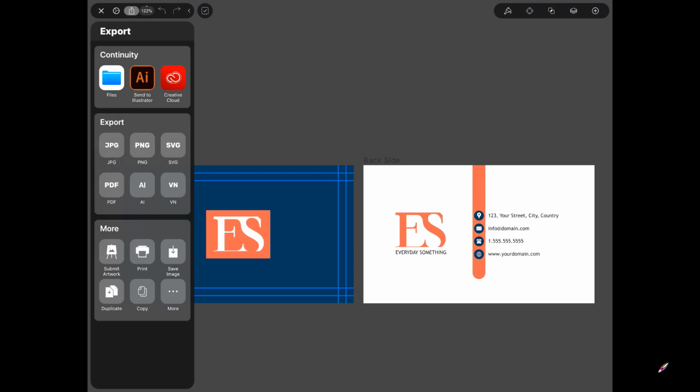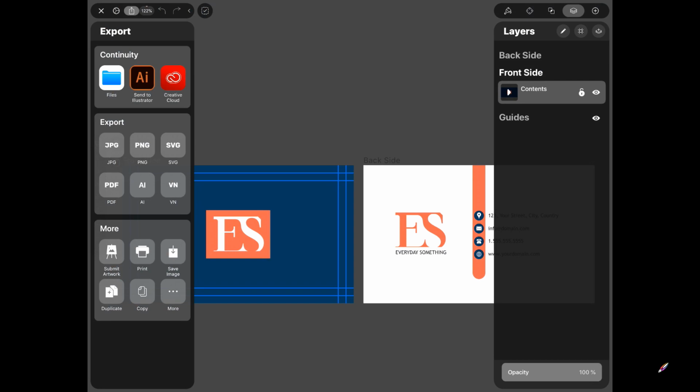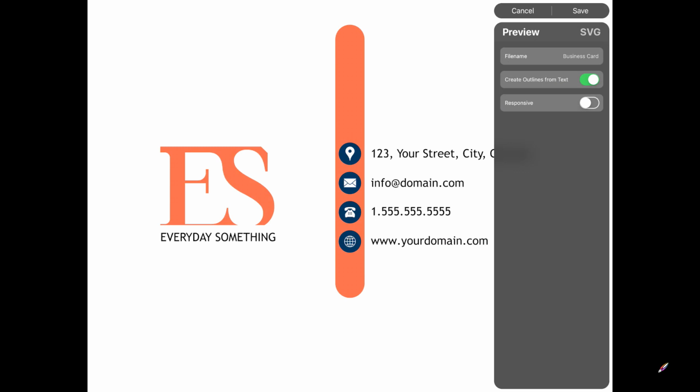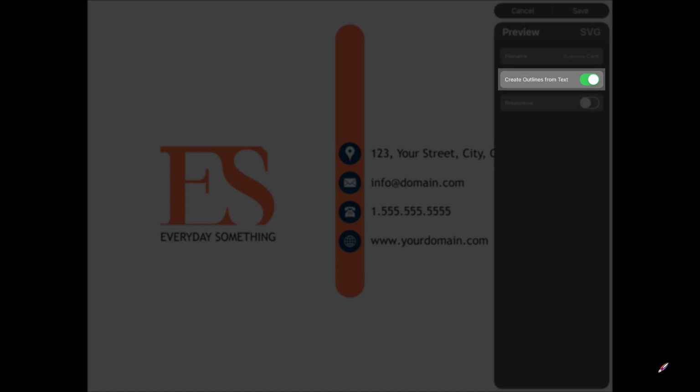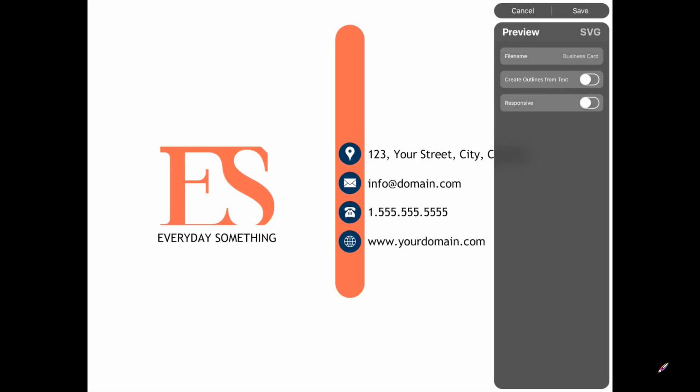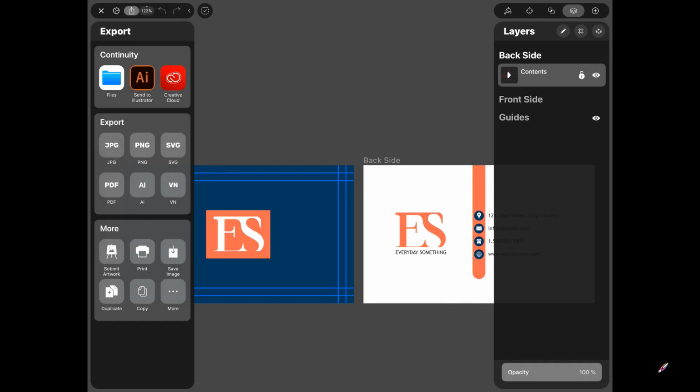Another option to consider is the SVG export option, which actually will export each artboard separately in this case. So I'm going to have the layers panel here, and I'm going to tap on the back side and then tap on the SVG icon to export that. Now in this case, I'm going to toggle off the function of create outlines from text, which will give you the ability to further alter the text, providing that you have the relative fonts, of course, installed into your system. Okay, so you can go ahead and save that and export it in these different export options.